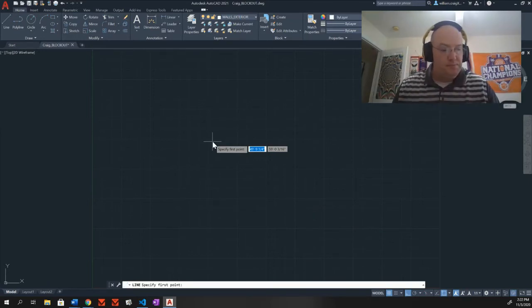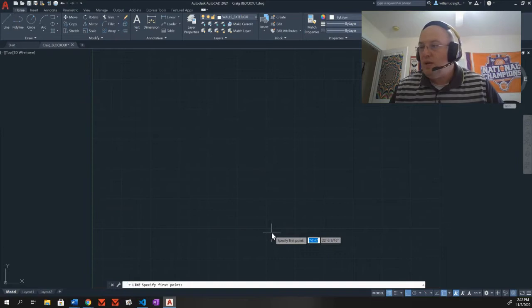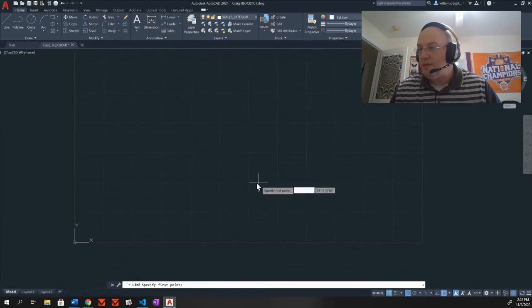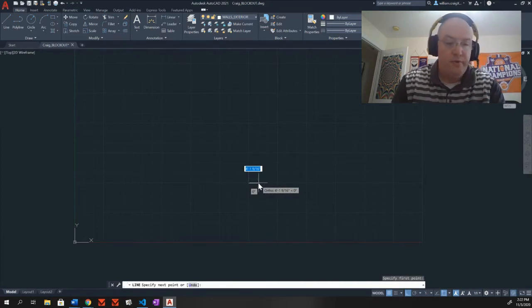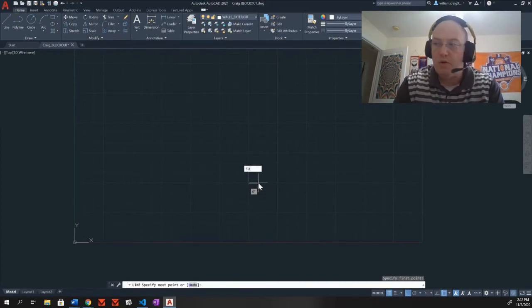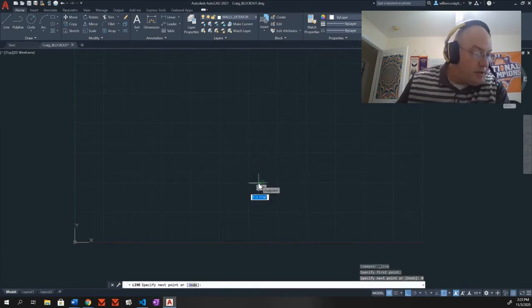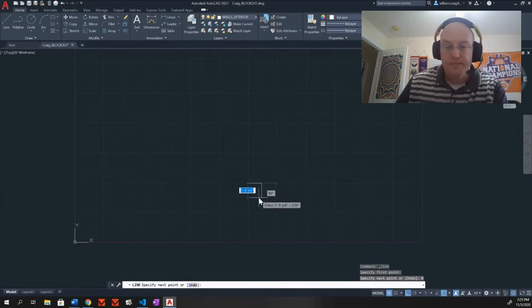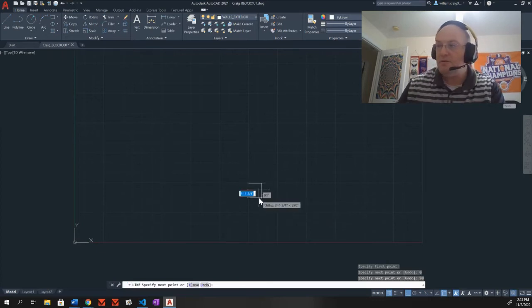So let's go ahead and draw this. We do not really need a starting point. I already have my line tool. Since I know I'm drawing the bottom right quadrant, I'm going to start down here, right about here. I'll click and drag over a little bit. I enter 5'4", tab, enter. Now I need to come down 2 foot 8 inches, tab, enter, perfect.